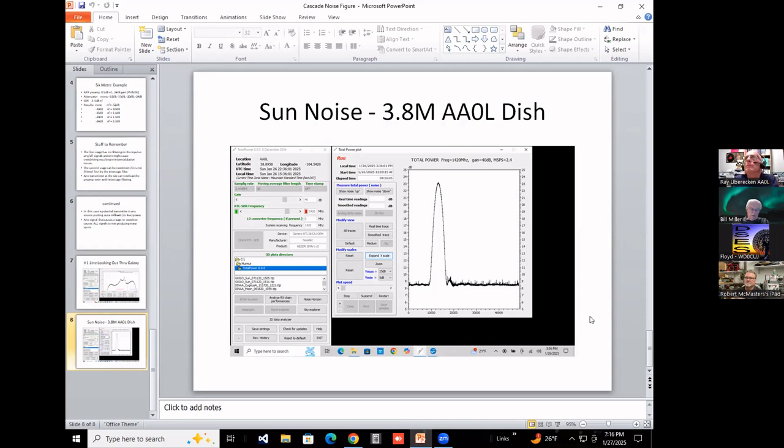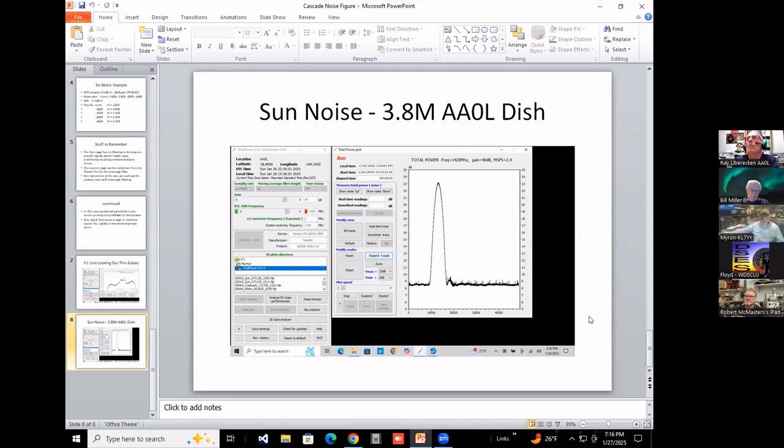What's your broadband preamp? What's the frequency coverage on that? Well, in this particular case, the coverage is much narrower because it's only for hydrogen. The bandwidth is about 30 megahertz, I think, something like that on this frequency. Are you using hardline for your coax? No, you gave me the cable, I think. It's LMR 400, 600, mostly. Yeah, LMR 600, the big stuff.